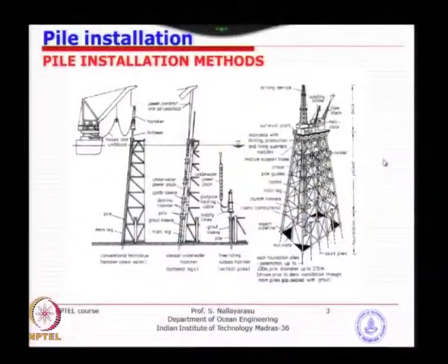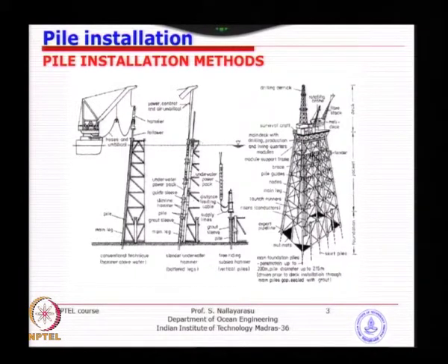Whereas if you go to the last one, you can see here the hammer has gone underwater. In this case, we have a vertical skirt pile and we have one single section, no welding is involved. Straight away you insert it into the sleeve and the hammer goes, you just drive and it goes underwater, also the hammer goes below. So you can see the equipment requirement for this is completely different. Here, this machine can be a simple diesel engine, which is very simple. So the engine can just pick up the weight and drop, pick up the weight and drop.